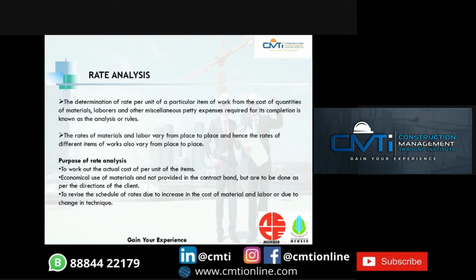Next, what is the purpose of rate analysis? To work out the actual cost of items per unit. Economical use of materials, which are not provided in the contract bond but are to be done as per the directions of the client. And to revise the schedule of rates due to increase in the cost of material and labor, or due to a change in technique.